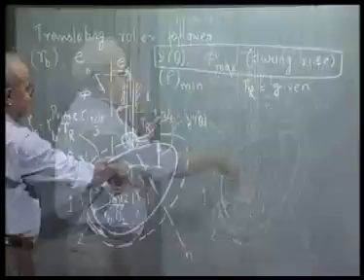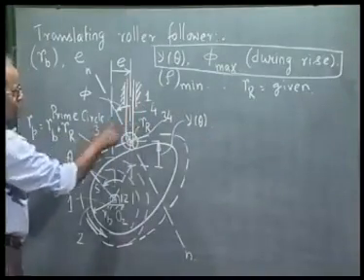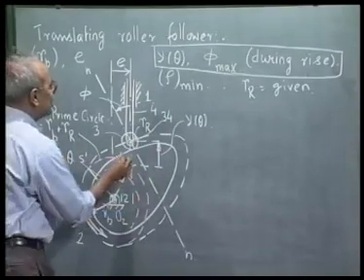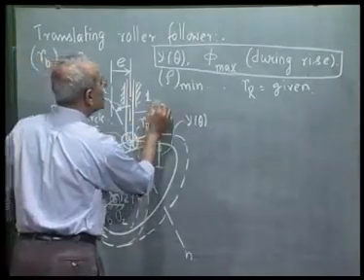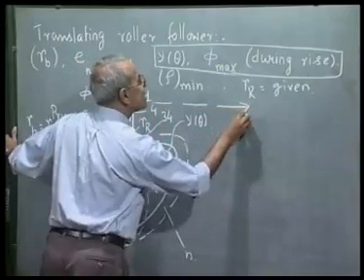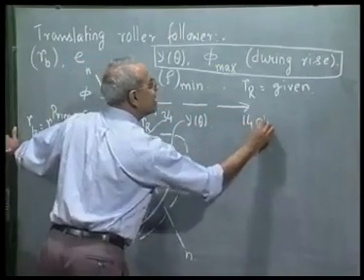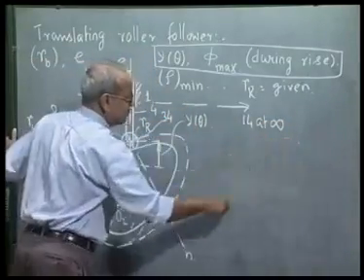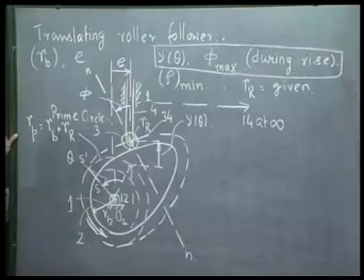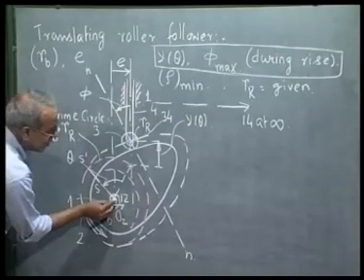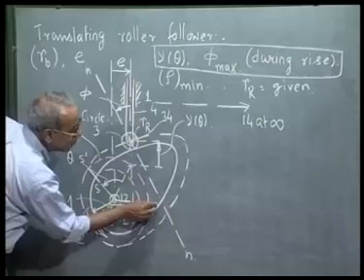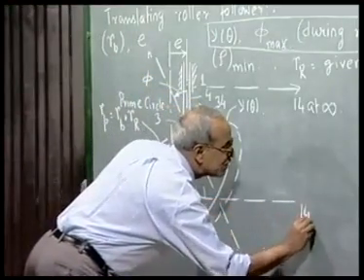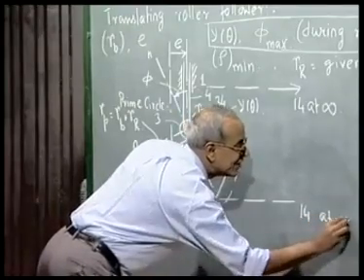4 is in vertical translation with respect to 1, so 1,4 is at infinity in the horizontal direction. I can draw any horizontal line and 1,4 lies at infinity because all parallel lines meet at infinity. So if I draw a horizontal line through 1,2, it contains 1,4 at infinity.